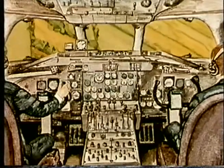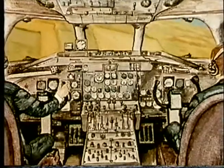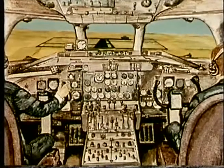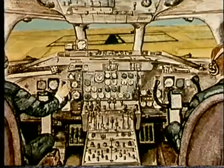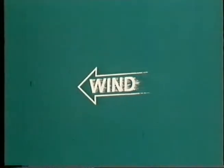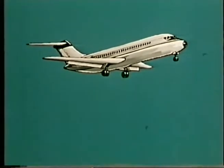By making all turns to the left when approaching for a landing or after taking off, unless otherwise prescribed or instructed. By landing or taking off into the wind, unless safety, the runway configuration, or air traffic considerations determine that a different direction is preferable.